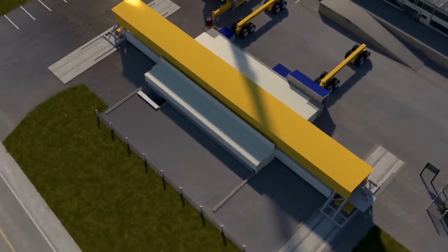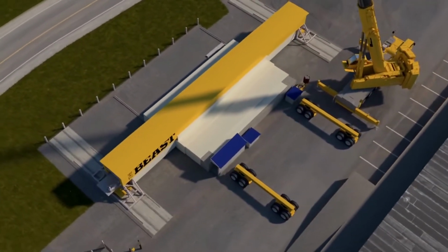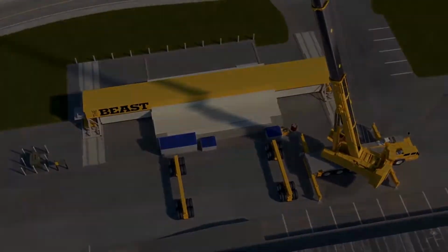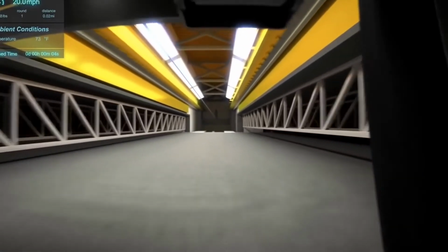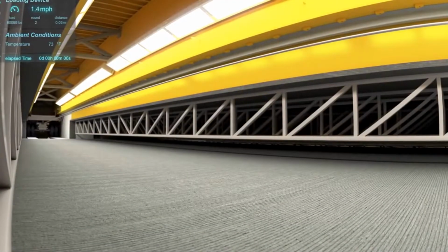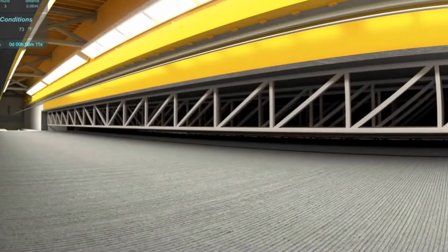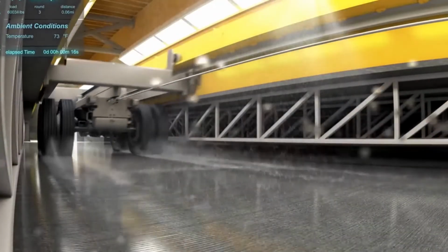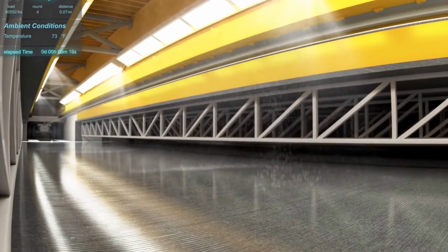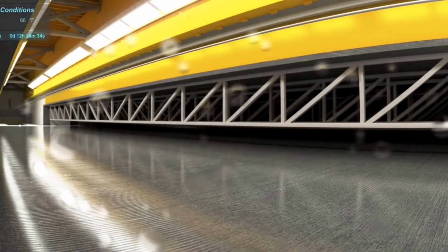So the way the laboratory is envisioned to work, the first specimen will actually be constructed in the lab, but in the future we have a yard off to the side where we can build these superstructures and bring them into the lab. The environmental chamber and the live load beam slide out of the way, so it's sort of open to the sky. Everything's on rails, so we can close the environmental chamber. We can locate this live load beam at any location, any width along the bridge.